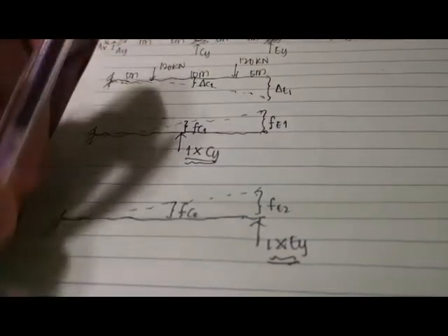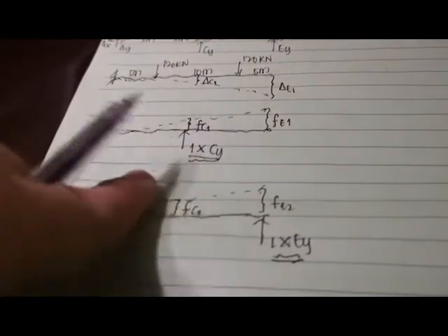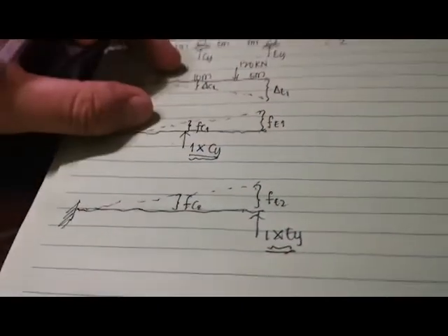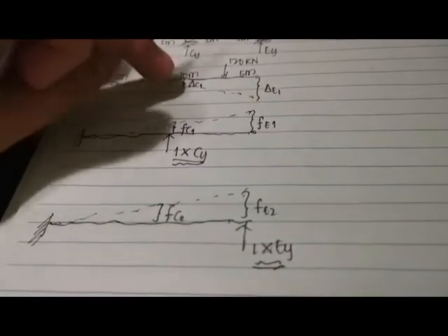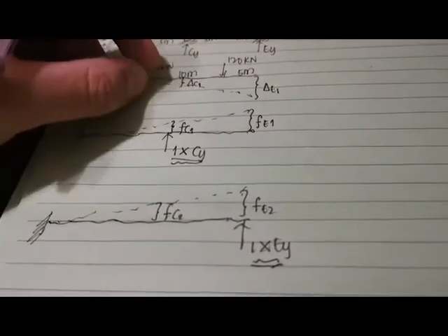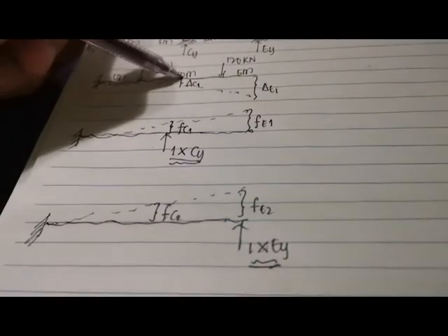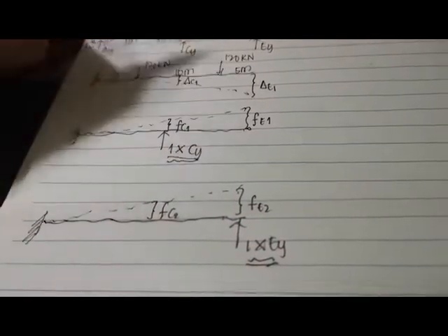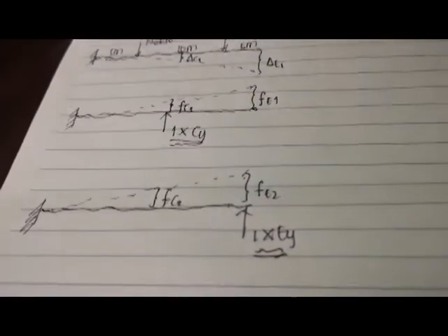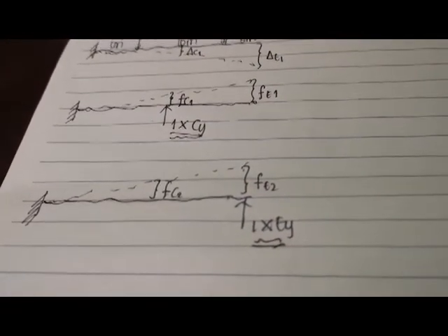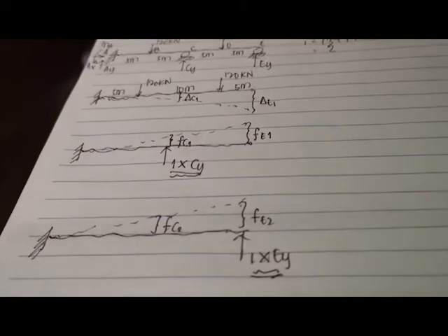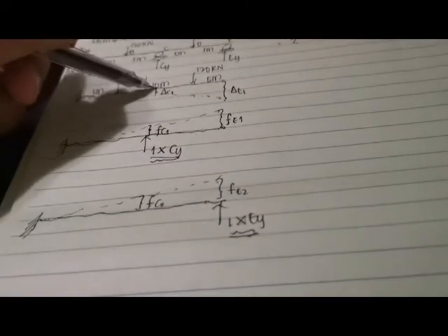But if we remove the loads and then just put the reactions, we know that it will go upward. So technically speaking, the reactions will just cancel out the deflection on the points you have considered as your redundants. So your working equation now will be just add all the deflections at point C and then add all the deflections at point E.